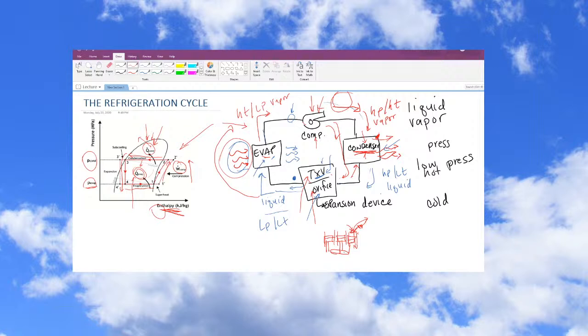And so if I alter the position or the angle of this plate, I can cause the pistons to move a further distance than they did before. So that's one way you can have a piston compressor that's a variable compression. I don't know, is that what you're talking about? Okay, right on, William.